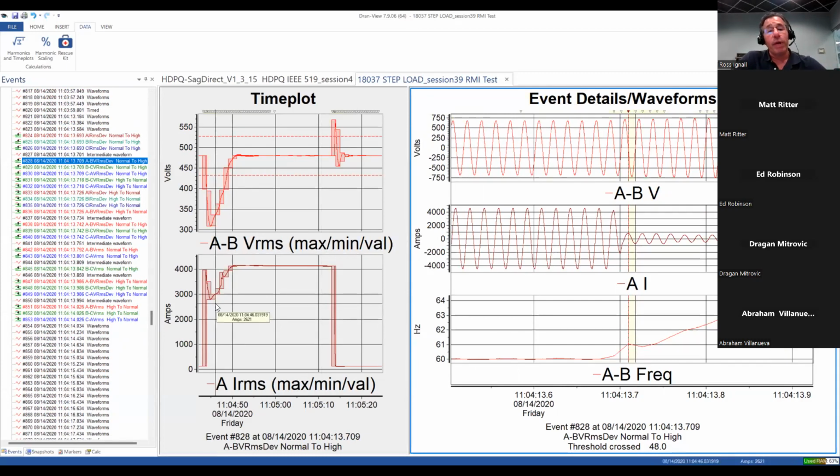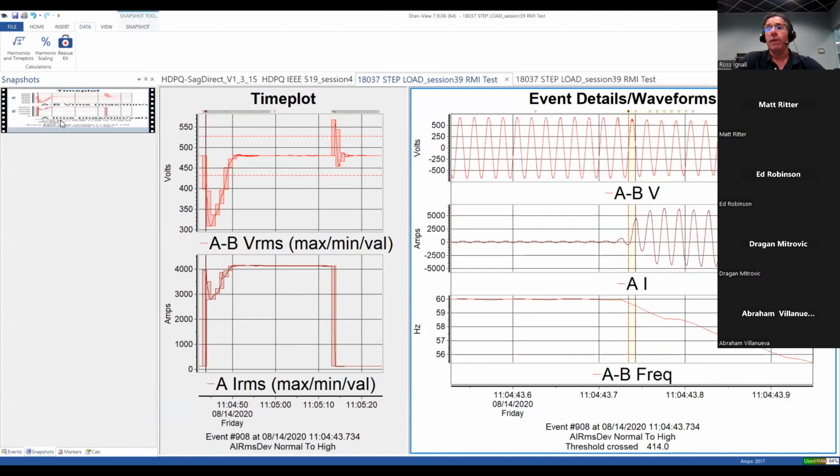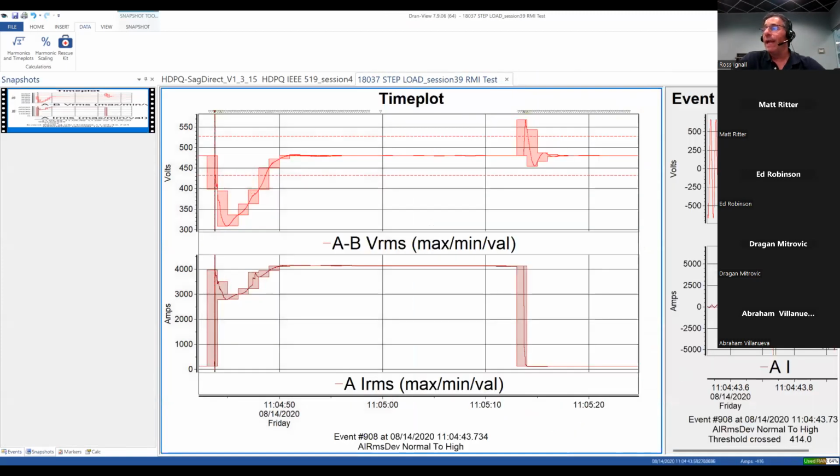But again, the motor inrush application, or the inrush or the cold load pickup, is very similar, but you're really looking for just that firing over here, like I showed you in the snapshots. That energization going from 0 to whatever it's going to max out and peak when it turns on. So it's very similar, but a little more specific and honed down application.